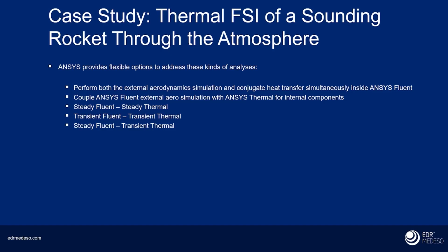Okay, the options for that kind of analysis are either steady, where you have a steady frame of reference, or fully transient. So if you think back to that deforming bluff body that I showed you, that would be a fully transient two-way FSI. Depending on the precise circumstances, you might be able to simplify that and have a one-way FSI. The difference is essentially compute time, but either one of these methods is available and made easy for you to do.